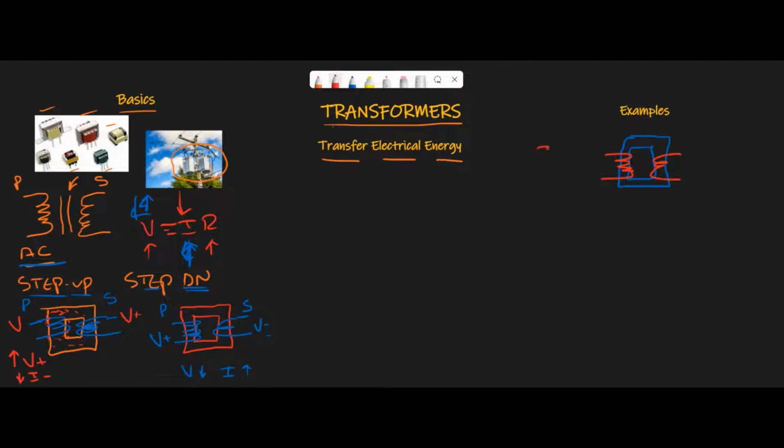And how this simply works is, let's say we put in 240 volts AC. Got to remember, we're operating in AC. And we get, let's say, 120 volts on the output. Again, this is the primary and this is the secondary, but really this is the input and the output. We can look at this in terms of being a 2-to-1 ratio. We're decreasing this by half, 2-to-1.